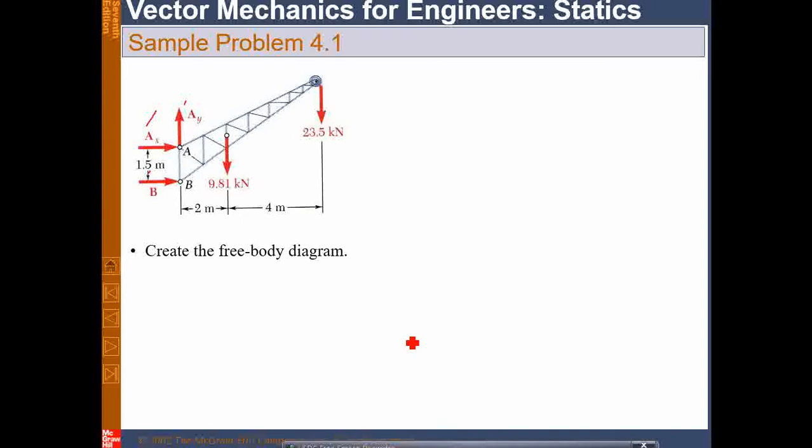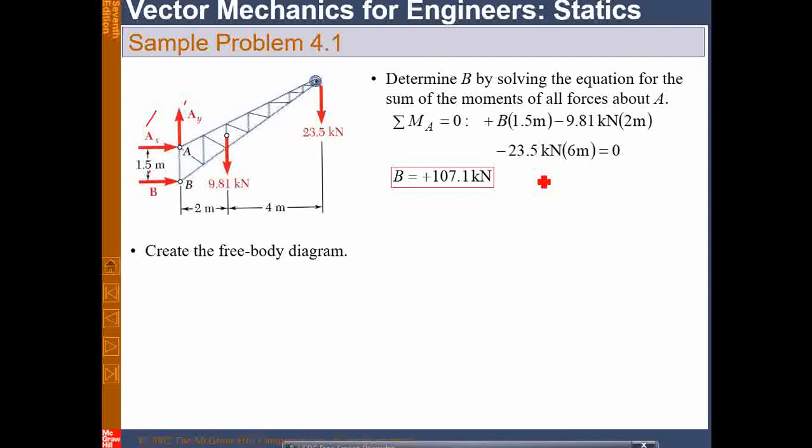We will find out the summation of all the forces equal to 0 and summation of all the moments equal to 0. So summation of all the forces along the x direction, and along the y direction. So let's first of all find the moment. The moment will be found at A, because A is the completely fixed location. This will be offering a two-dimensional moment also, because this is completely constrained. So summation of all the moments about A.